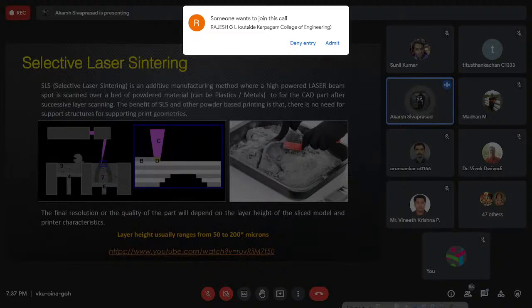So what people did was add a kind of optics, which is called an f theta lens. It's a really expensive lens they use to correct this distortion, to make the beam on the ends as close to a circle as possible. It'll never be a circle, but it's as close to a circle as possible.